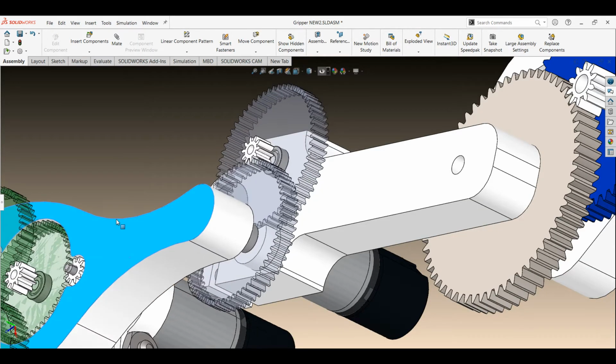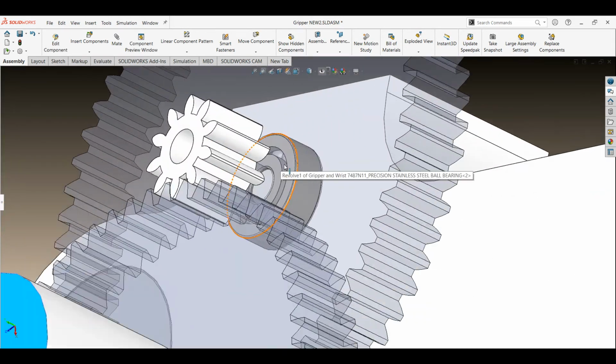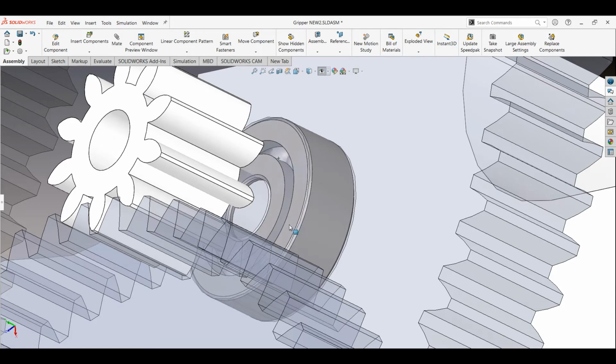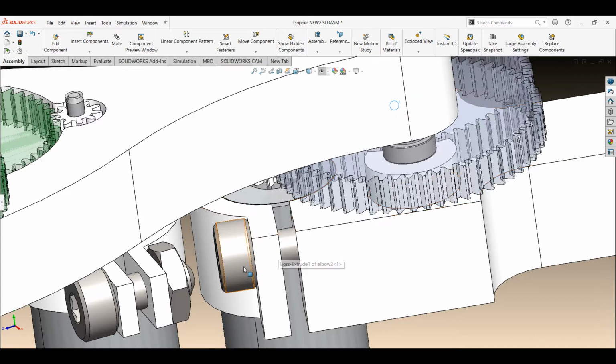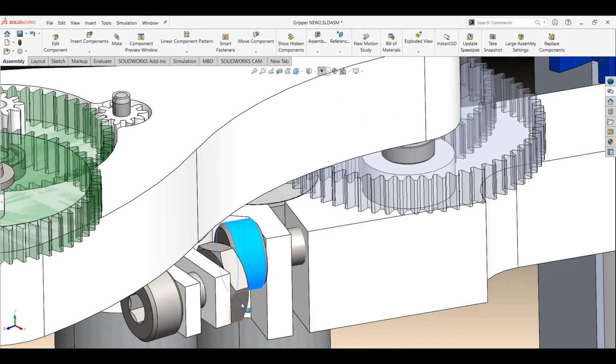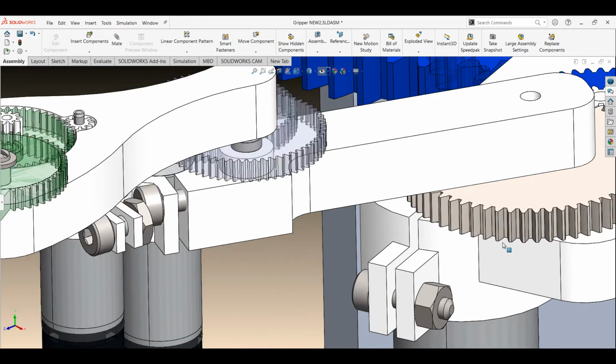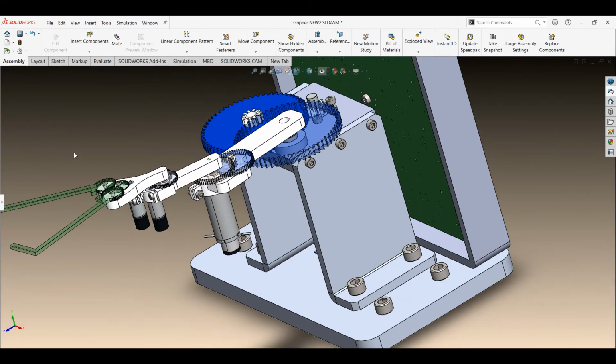You can see here the ball bearings for the wrist motor, as well as the standoffs used to secure them and the gears. The same thing for the elbow motor and the shoulder motor. Another detail here is that rather than using a heavy metal nut, the M2 screw for the wrist clamp takes advantage of the shape of the forearm.